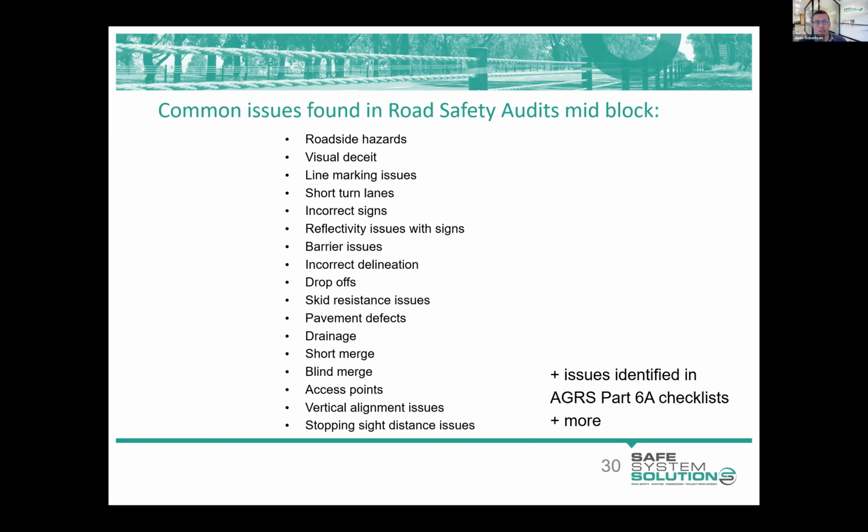It's a good question, and probably the guidance is a little bit grey in this area. Do you consider things like trees and poles near intersections as sight distance impediments? Well, they certainly are to some extent, but usually, if something has a fairly small diameter, you can sort of see behind it or in front of it. It depends on your road geometry approaching the intersection, how much of an impact it can have. So I don't have a magic number in terms of size for you, but it's very much a case by case thing.